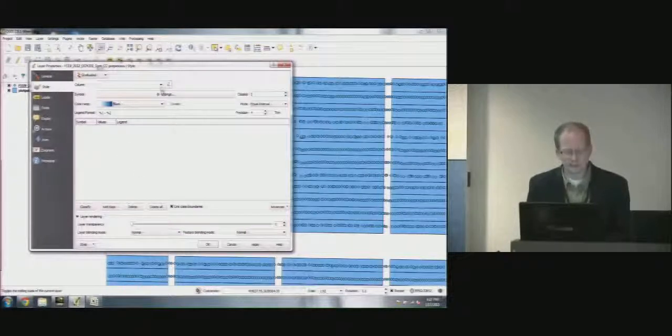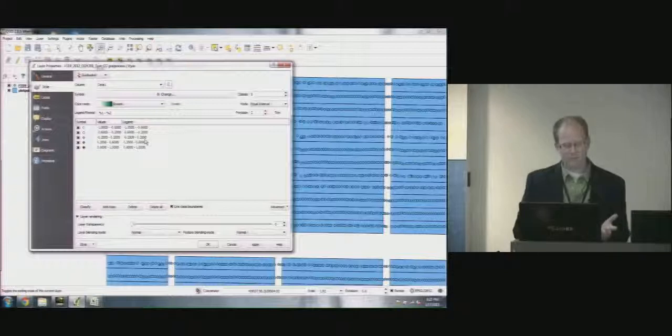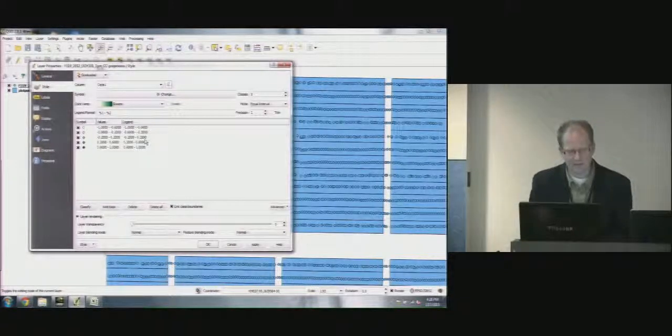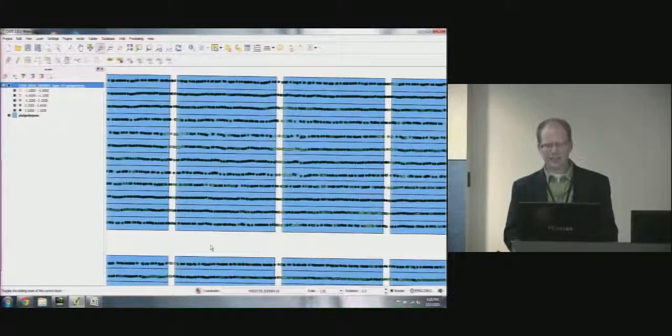And let's say we're interested in Data 1 column. Say classify that information, and let's use something other than blue because our plot map is blue. Let's use green. That'll be good because this is sort of an NDVI, so darker green should be higher NDVI and should represent more vigorous vegetative growth. Apply that. Say OK. So there you can kind of see some of the variability of the data within the plot.